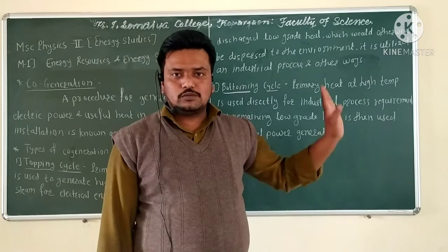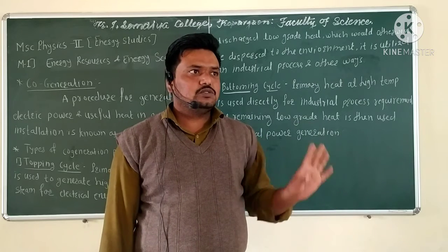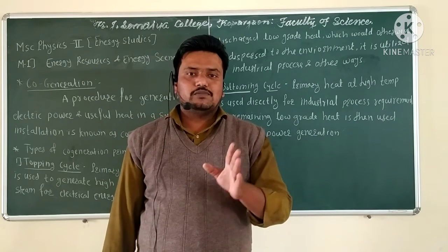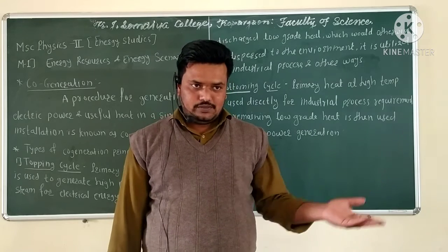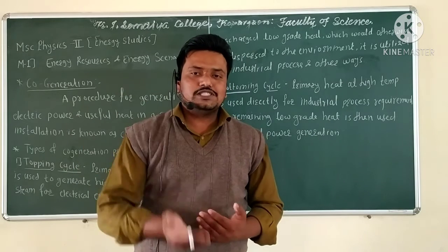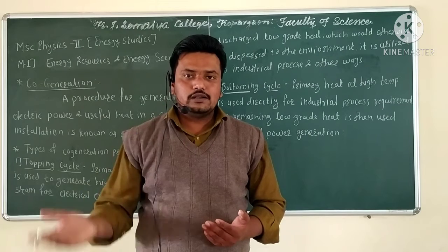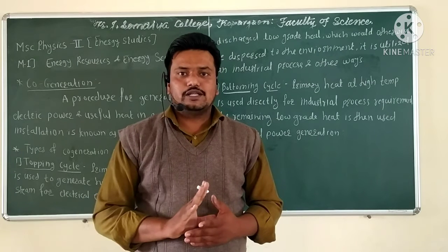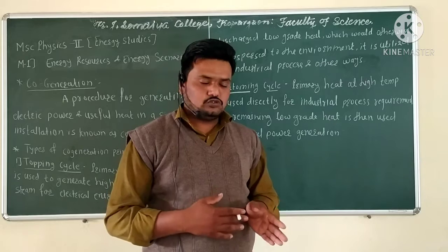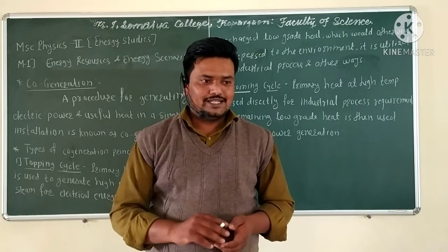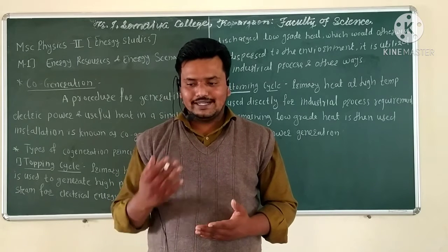Vice versa for the bottoming cycle: the primary heat is first used for the industrial process requirement, and whatever remaining part of the heat is used as low grade heat for the generation of electric power.